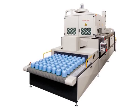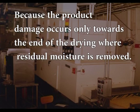Thus, the product can never be overheated and the product damage can be completely avoided. However, due to high cost, RF drying is used only for the finished drying after hot air drying is carried out, because the product damage occurs only towards the end of the drying where residual moisture is removed.